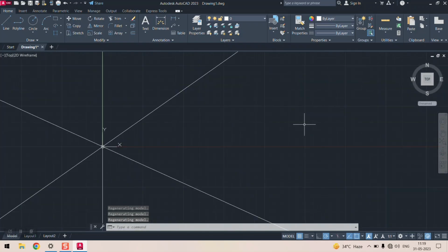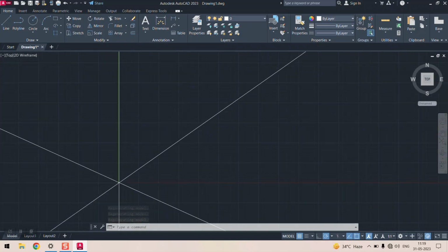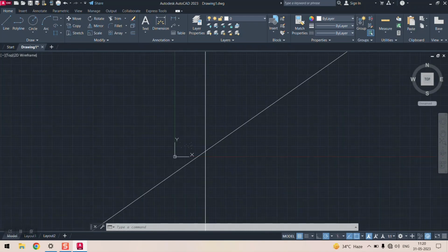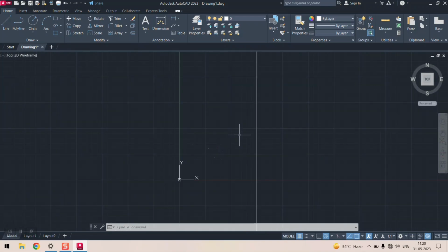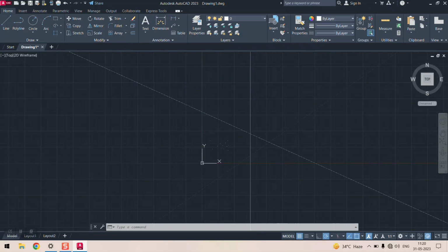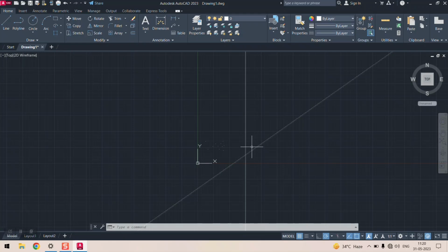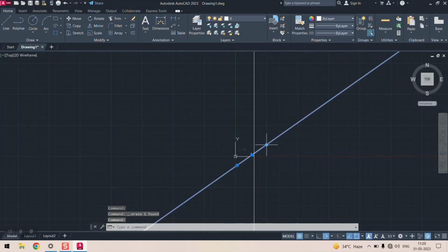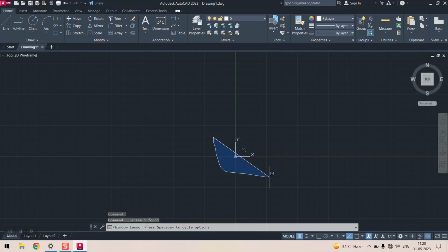A construction line will be created in such a way as to divide the entire part into a particular region, so that we can create the particular drawing or format in that area. Now I will do one thing. I will just click delete on this. Click on this to delete. I don't need them, and even these points.